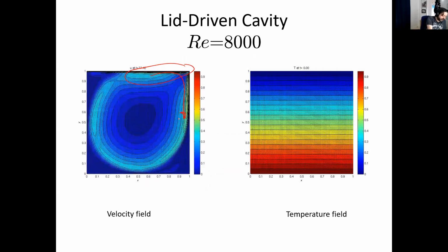Also here, a very thin boundary layer developing, and then the flow goes around in a nearly circular way. You can also see, if you look carefully, that there are some secondary vortices. If this vortex is going in this direction, then you will have some secondary vortices in the corners that are being driven by this main vortex. I guess there would be even one on top.